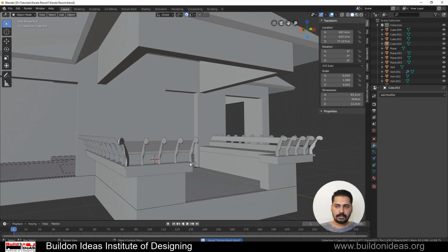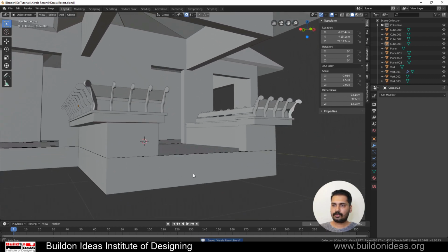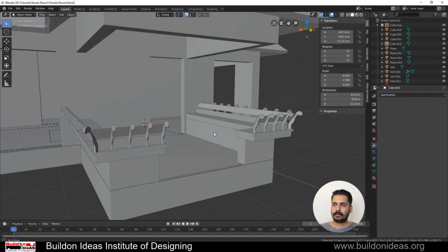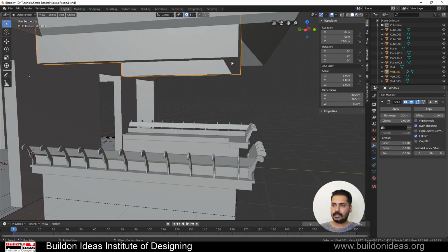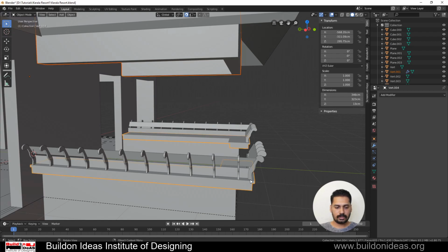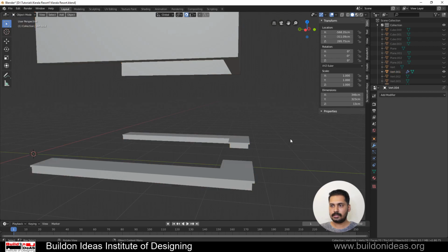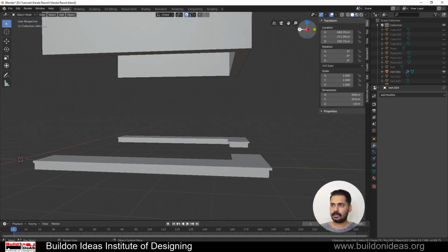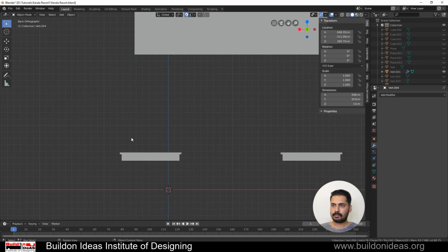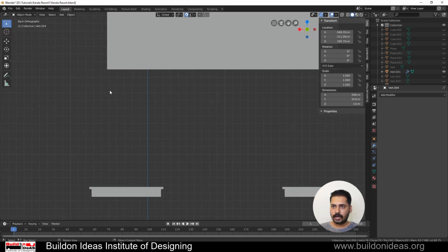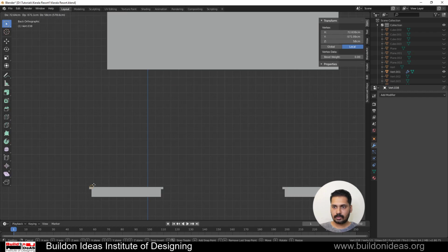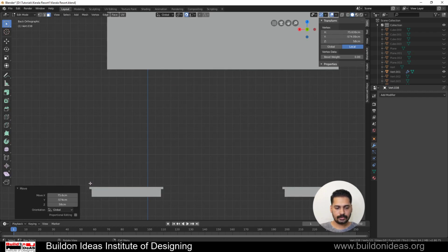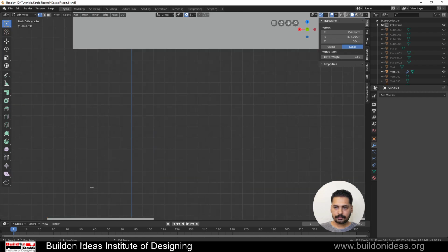Now what is required is, just click save. I have to create the pillars for this. So I'm creating a particular kind of shape, that is a traditional shape for the pillar. For that I'm selecting these two and then hiding everything else just to have the size of it, and then I'm creating the pillar. So in order to have the pillar, I'm just adding a single vertex. I'm just grabbing it to the position, just the edge for the time being.